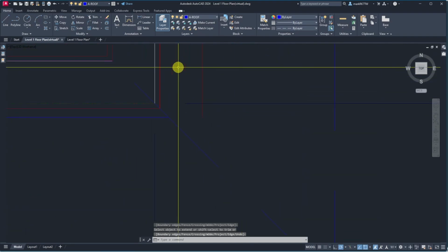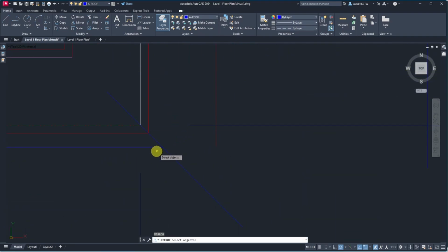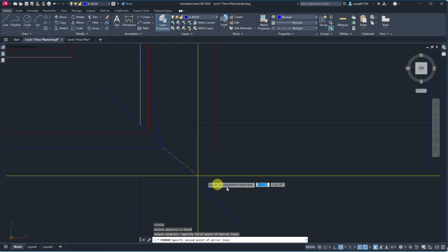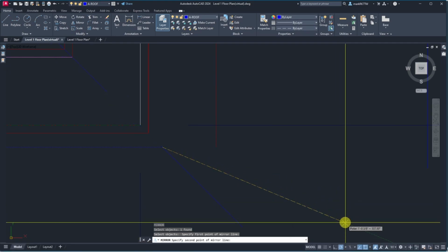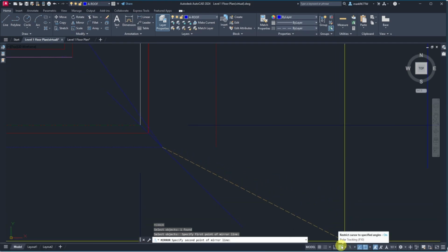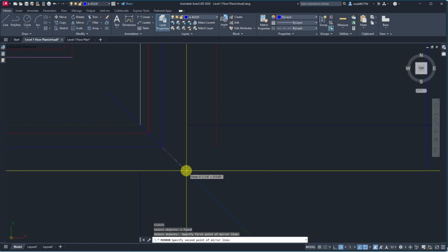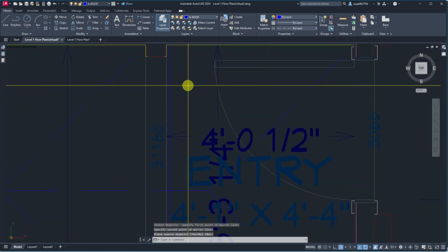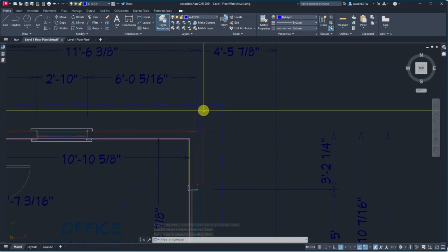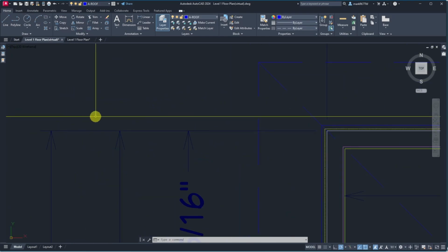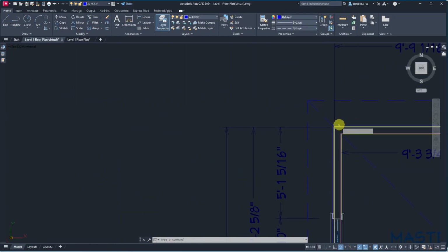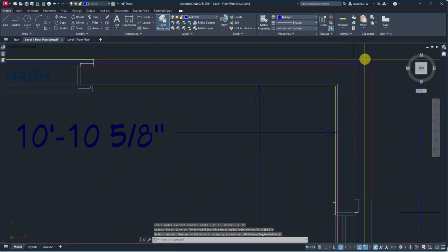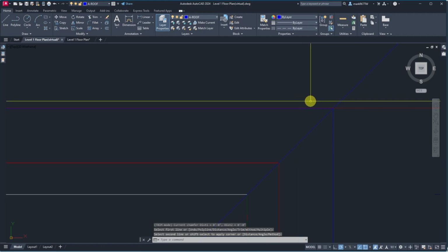And then one of the tricks I'll use is I'll just mirror that around a 45 degree. I happen to have a line here, but if your puller snaps down here to include a 45, then you can also do this without even having a line there. So I've done that, and now it's come all the way across, and I do have to trim it out, but it's there. So now I've got siding all the way around the house. This stuff out front, that's brick.